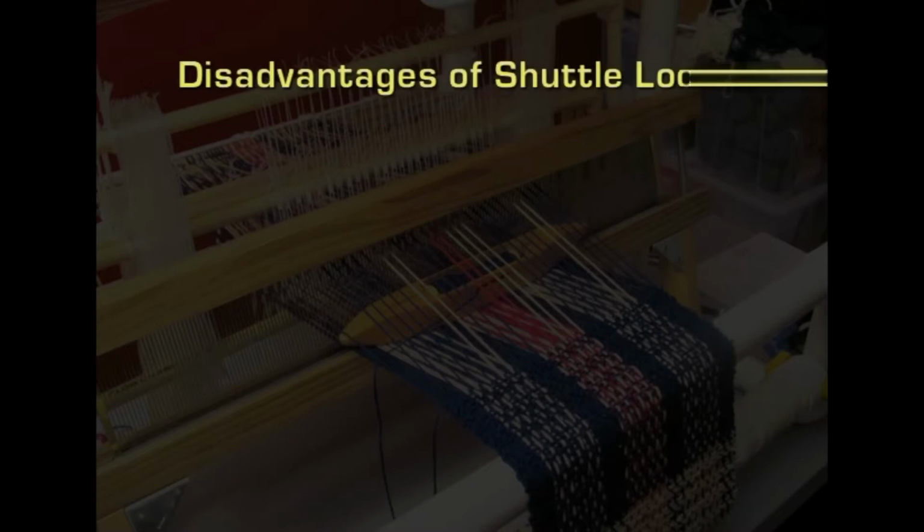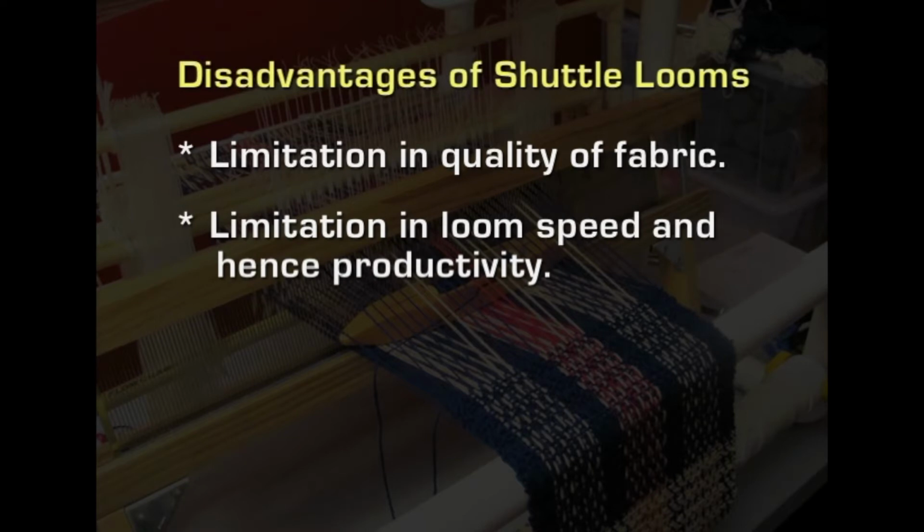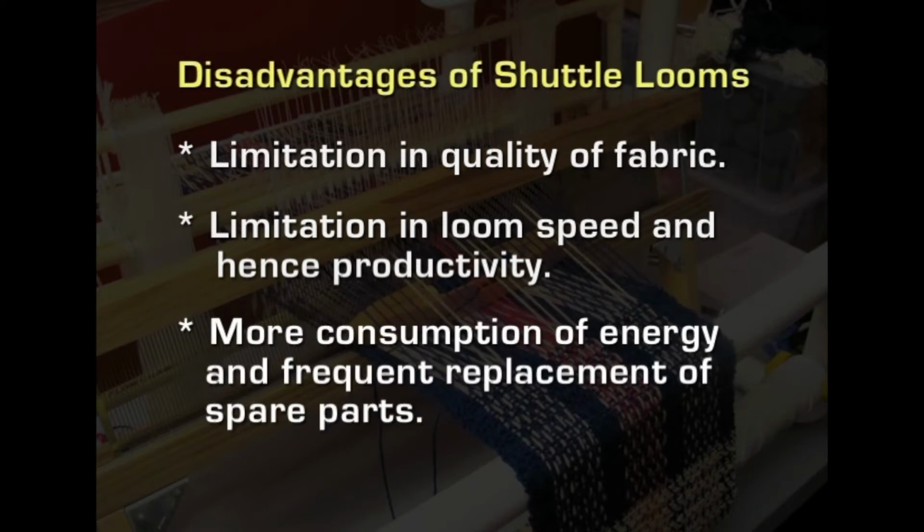Now due to all these reasons, shuttleless looms were required. Disadvantages of shuttle loom. The most common disadvantage of shuttle loom is that there is a limitation in the quality of the fabric, there is limitation in the speed of the loom, and hence the productivity is reduced. More consumption of energy and frequent replacement of spare parts. To overcome the above limitations of the shuttle loom, the need for a better weft insertion system was felt.